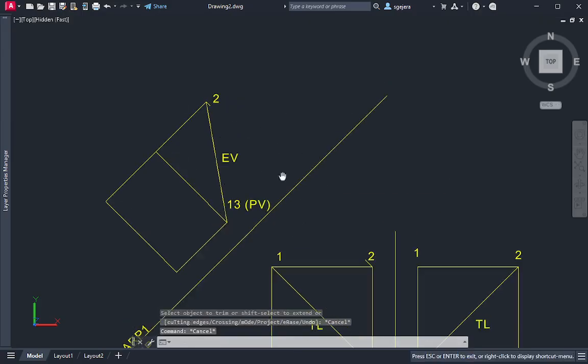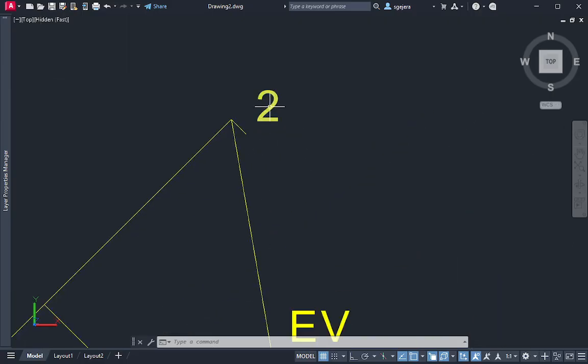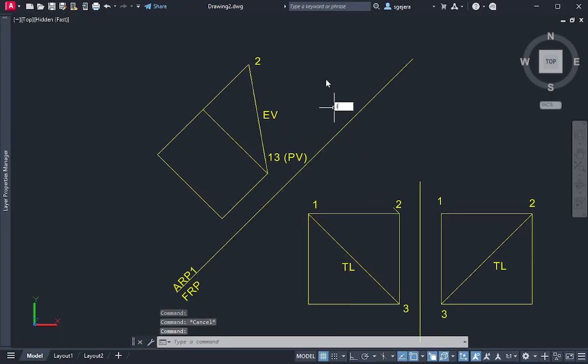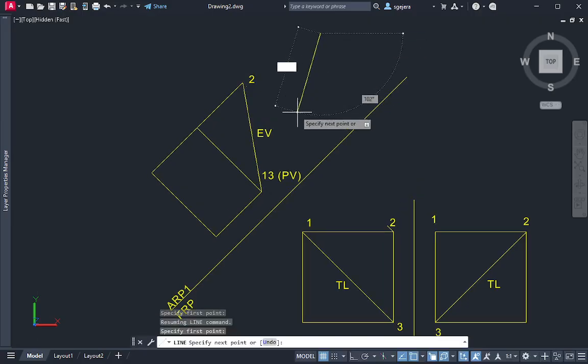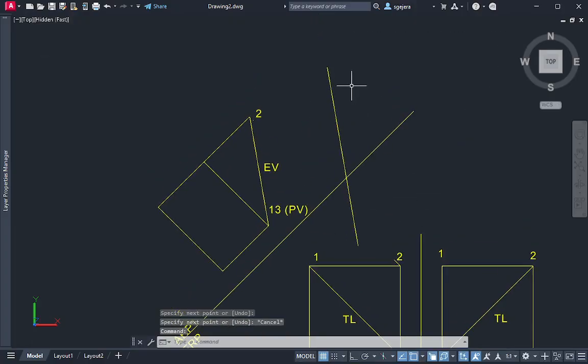Right? So, ito, hindi pa siya tapos kasi, let me just remove the projection lines para mas malinis. Hindi pa tapos kasi what we're shown here is still the edge view of the oblique plane. Pero ang kailangan kasi natin is the true length of the, or sorry, true size of the oblique plane. So we need to create another reference plane. So what's the reference plane that we need to do para ma-expose yung true size? Parallel to the edge view. So gawin natin is, let's create a parallel to the edge view. And let's just label this as ARP2, no?